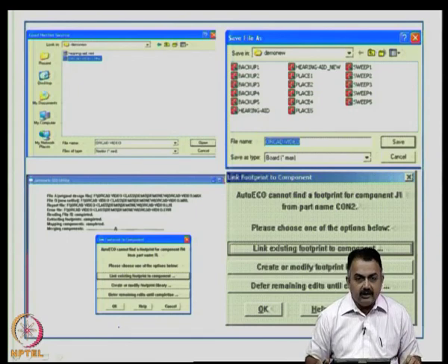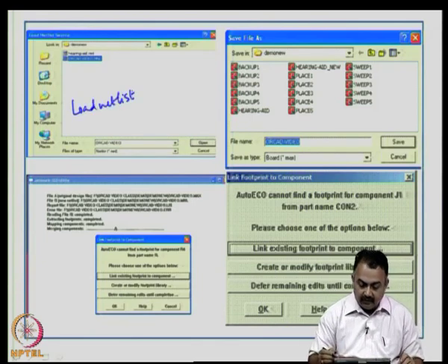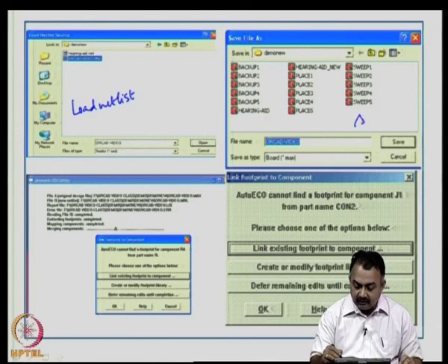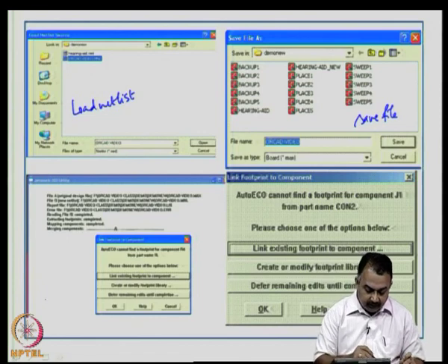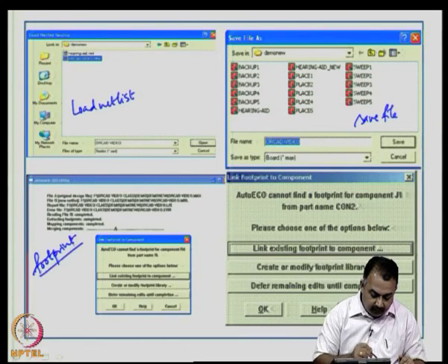So, what this slide essentially shows you is some captures from the process. You can see here loading the netlist which you have generated, then saving it as a new file name for the layout package. Then here you have to tag, some packages will ask whether the footprint information that you have referred to in the schematic can be loaded.